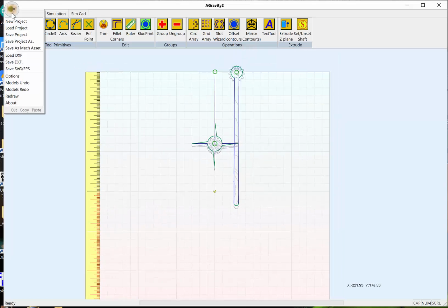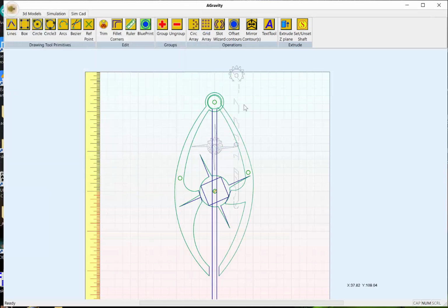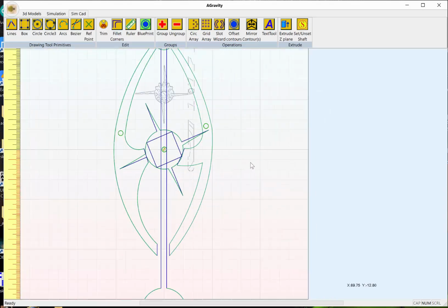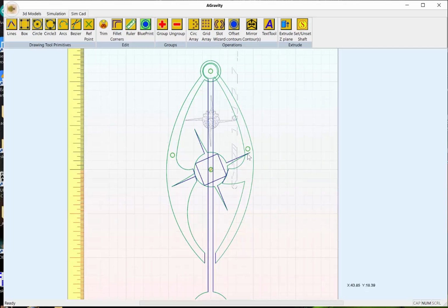Now let's take a look at that in mind with a project that I was doing earlier today that is actually workable. And here's an escapement, which is a type of gravity escapement. You can see there is a cam block on top of the 4-pin ratchet. And my surface where I'm going to hit the pins is at 90 degrees to the pivot pin. When this pallet pushes out, this pin will slide forward to hit this pin, which will lock it there, and during that time this cam will push this pallet outwards.